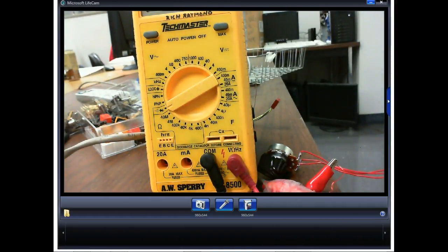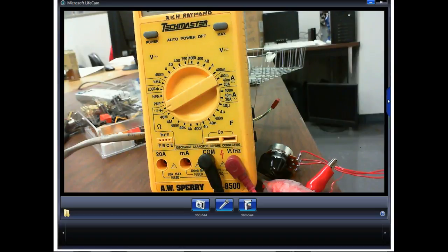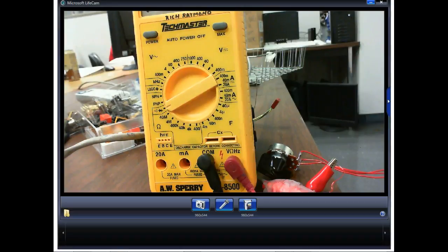So now all you got to do is put this lead over on this side and touch that on. If it's a straight piece of wire, can you hear it? And so you don't even have to look. So we find continuity all the time, checking fuses. Fuses have very low resistance when they're good. They have infinite resistance when they're bad, right? You understand? So we check fuses all the time. So y'all need to get used to checking fuses.